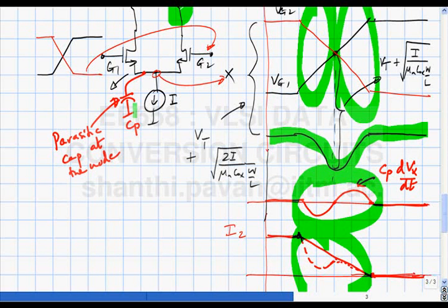Basically, parasitic capacitance at this source-coupled node causes a glitch, and if you go into a careful analysis of the waveform and do the math, it turns out that this causes distortion. Can you give me an intuitive feel for why this results in distortion?